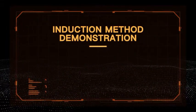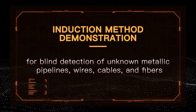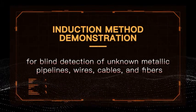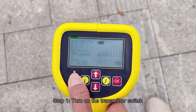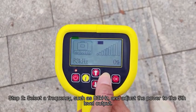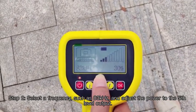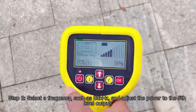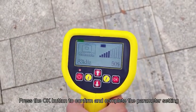Induction method. Demonstration. For blind detection of unknown metallic pipelines, wires, cables, and fibers. Instrument operation steps. Step 1. Turn on the transmitter switch. Step 2. Select a frequency, such as 83 kHz, and adjust the power to the 5th level output. Press the OK button to confirm and complete the parameter setting.